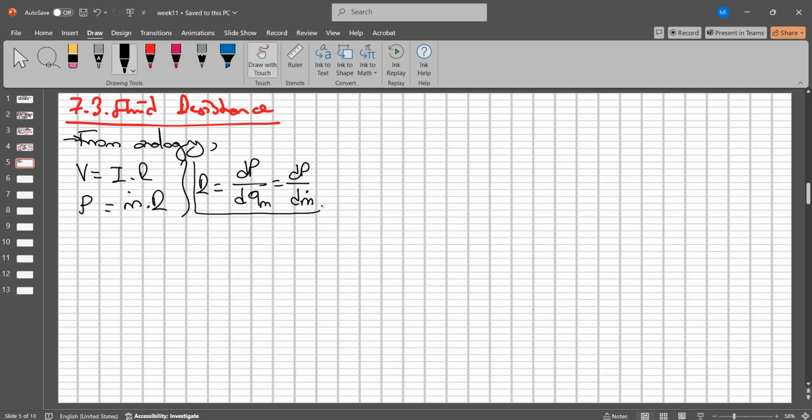Okay? This is the standard basic mathematical definition of the resistance value. And so, we can derive this. This is the derivative. And so, this is M dot. This is the P. And we can take the M dot reference and P reference. This is the reference value. And so, we can draw this. And so, the tangent value is equal to R. That's the basic definition, right? That's so simple. You don't need to worry about anything in the system dynamics.